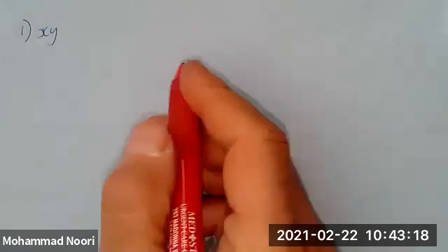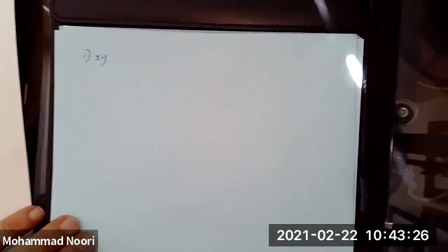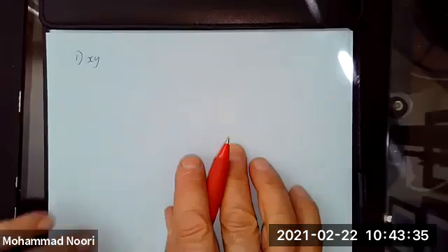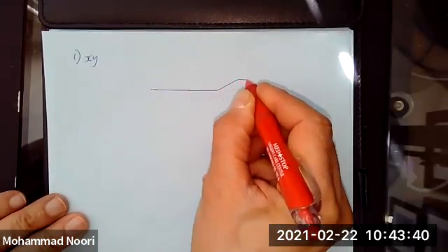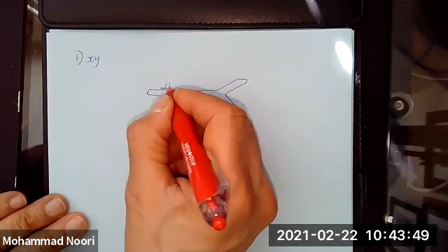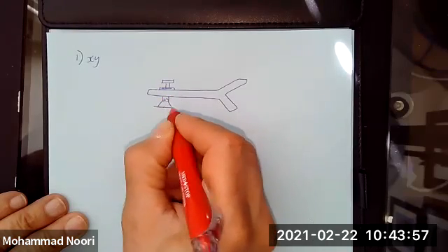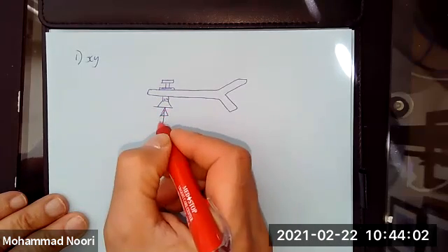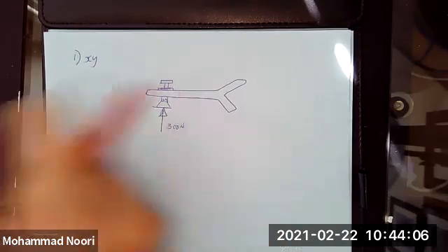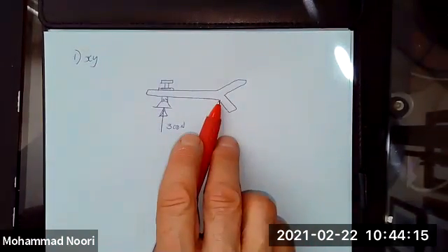And you try to set up the free body diagram, okay? So this is the free body diagram. Maybe I'll bring it down a little bit, okay? So I will draw the free body diagram of these two pieces first. So let's do that. The dog bone part, which is a piece like this, which has all these fancy stuff, the screw attached to it, whatever this is, okay? But the bottom line is, this is designed to apply a force of 300 Newton on this. So that force of 300 Newton is acting obviously upward on this piece, okay?